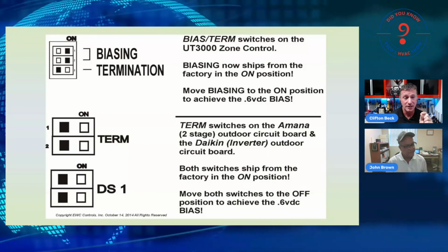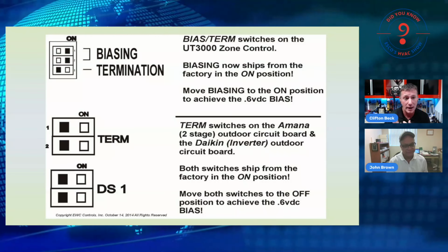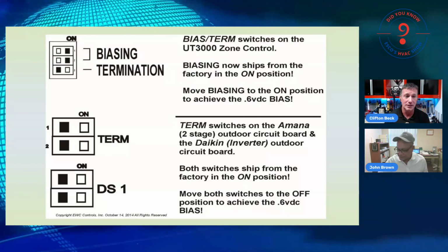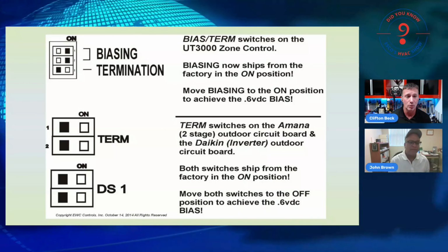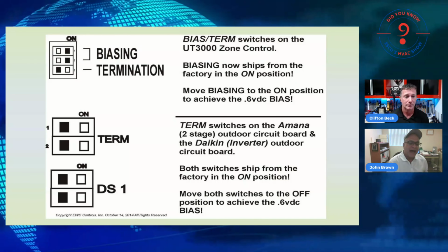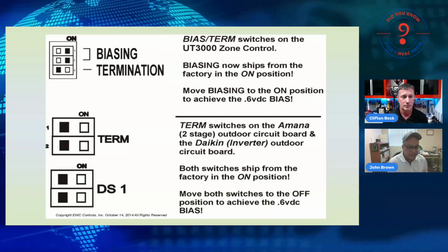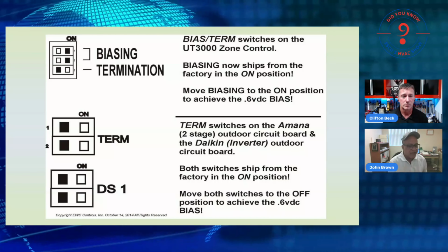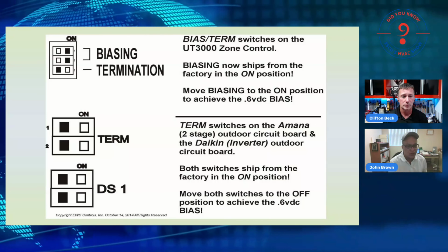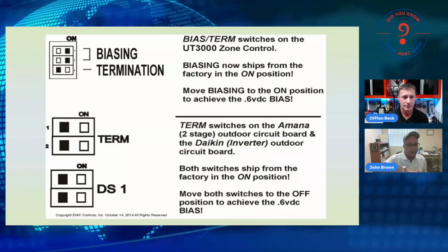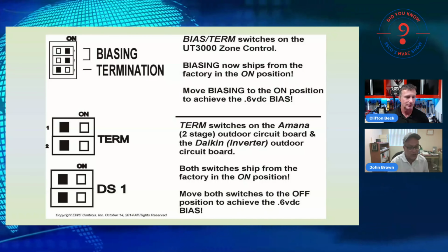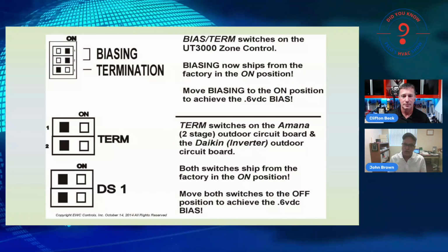The most accessible location you would think is right where you land your power wire, and that cover on the side of the unit. That is DS2. DS1 is actually located on the control board next to the display. To be specific, the DS1 or the term are typically very close to the low voltage terminal block where the factory black and factory gray wires actually land and terminate. Exactly. So 2 ways, gentlemen.